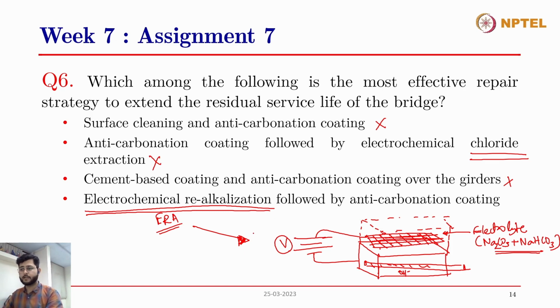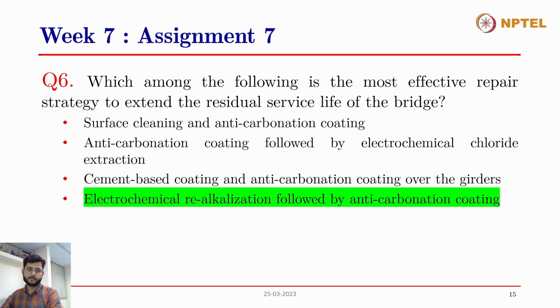Now, if you apply anti-carbonation coating over the surface of the concrete, that will prevent further carbonation from occurring. So that will again protect the steel reinforcement, and in this electrochemical realkalization process, the service life of that repair work will be enhanced due to the application of the anti-carbonation coating, because it will prevent the carbon dioxide from getting inside the concrete. So this is the right answer. I hope this is clear. This is a very good question.